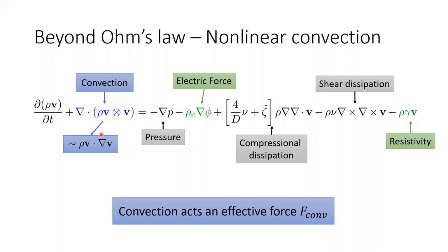And what is interesting about the Navier-Stokes equation, particularly for us, is that you get this convection term because velocity is a field. There's a convection term coming from the fact that you need to conserve momentum fluxes. And it is precisely these two powers of velocity which drive you outside of this linear regime and will give rise to the physics that I'll be discussing.